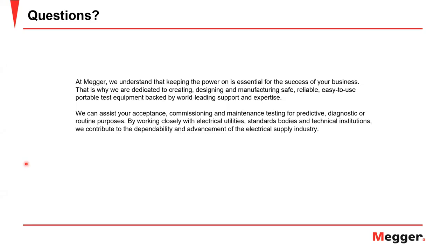The fuse saving scheme will be good because it will increase the reliability in indices like SAIDI and SAIFI, but it will decrease the momentary indices, because there would be a lot of momentary issues that would happen.